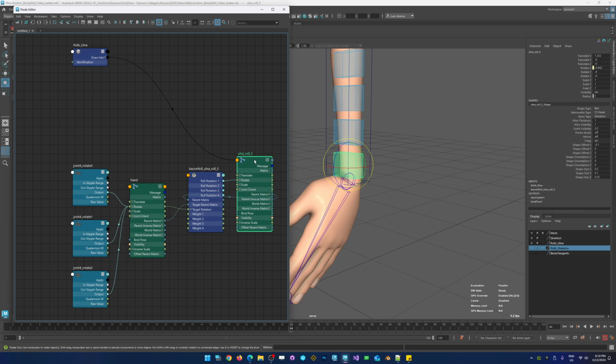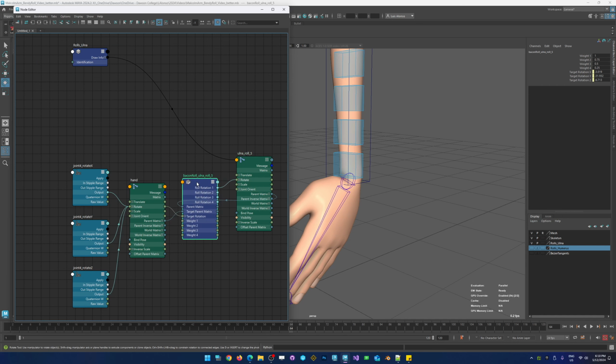But for the most part, it's just a constraint, a reference, and it's doing the rest of the heavy lifting for the rotation. And the thing is, everything in Maya references an Euler rotation. But what you do with that Euler rotation is what makes the difference. If you use it directly to do your twist bone, then you're asking for a bad time. You're going to have a bad time. If you convert that into a quaternion, or better yet, into a transform matrix, much more reliable math that can give you much better results like you're seeing here. Okay, and also we're not creating any extra reference nodes or anything. There's nothing. It's just a little constraint node, and that's it.